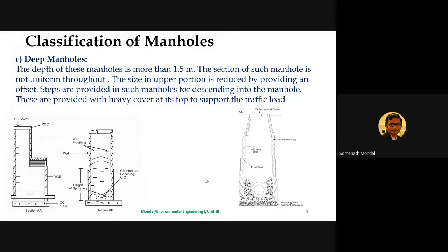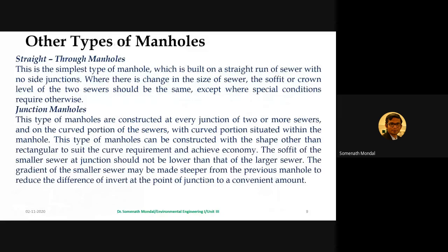And if we don't provide a heavy cover, it is difficult because such a huge void is there beneath that particular cover. So that is why heavy covers are always provided in case of deep manholes. And they can actually support the traffic load. So remember these different three types of manhole.